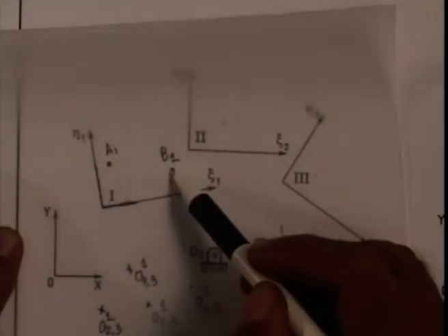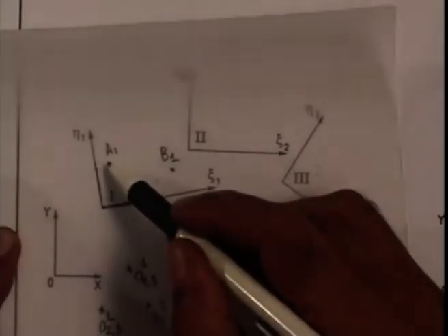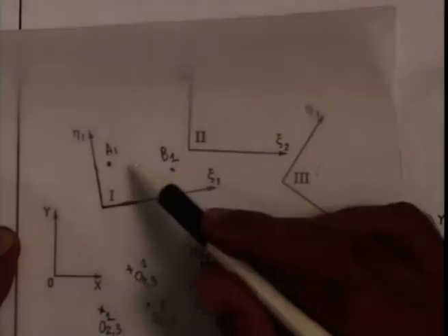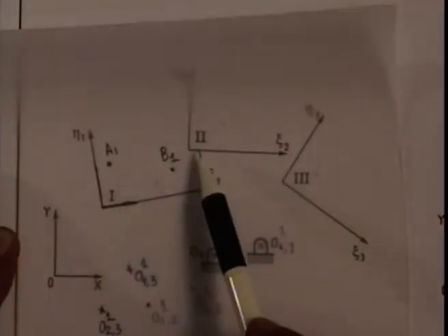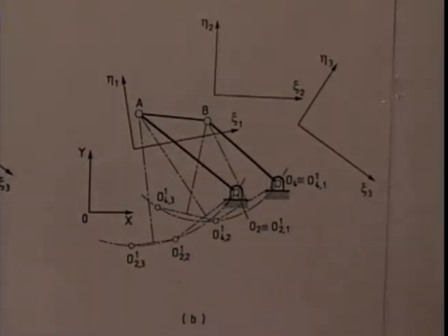So now we have located the required position of the moving hinges, such that if O2, A1, B1, O4, these 4 are linked and moved, the coupler goes from position 1 to position 2 to position 3 with O2, O4 as the fixed pivots. As the principle of kinematic inversion forms the basis of this procedure for dimensional synthesis, let me repeat it once more, the solution shown in this figure.